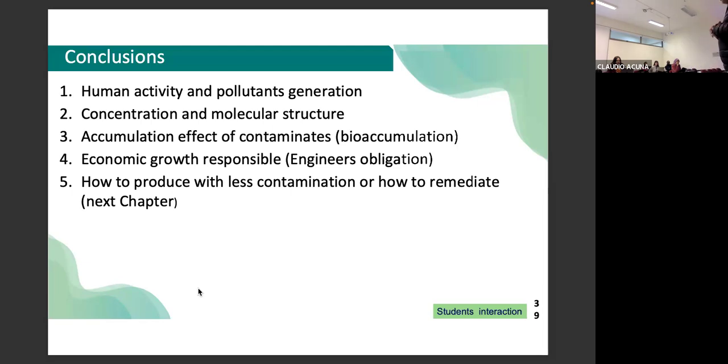Sulfate is a very good topic to study. Either membranes, or precipitation. Precipitation is also limited because you end up with a sludge where, the finer the particles, you will end up with a lot of water. You know what I mean? Fine particles, you will have capillary retention.